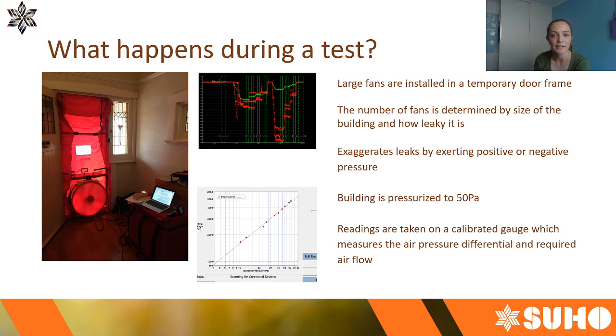So what happens during a test? Typically, somebody will come to your building site or to your home or your office location with some equipment. How much equipment we bring varies depending on the project. But essentially, we load some fans into a temporary door frame, which is installed in one of the external doors in the building. The number of fans we use is determined by how large the building is and how leaky it is.